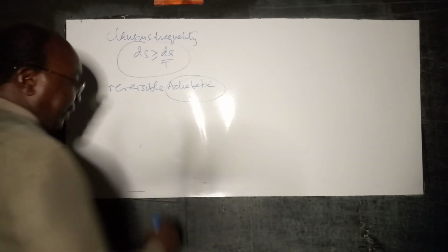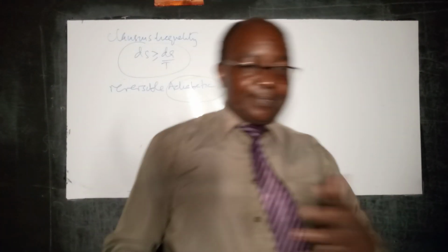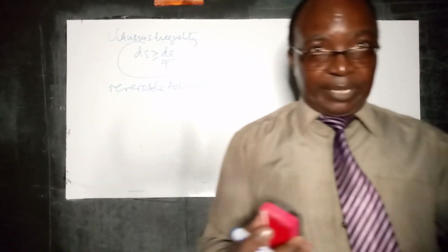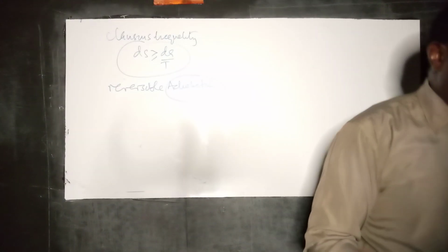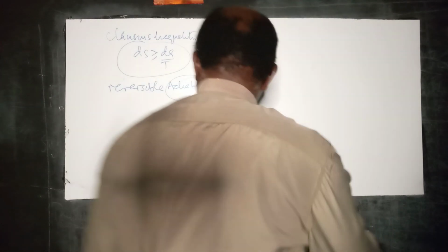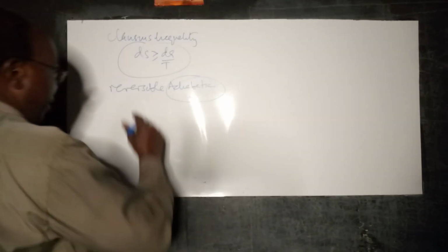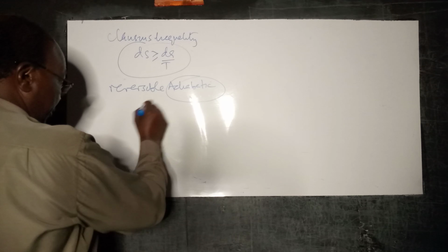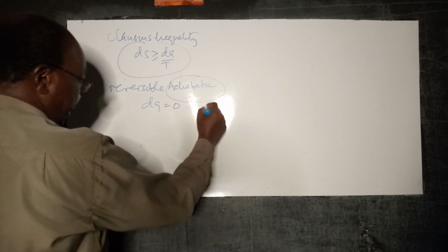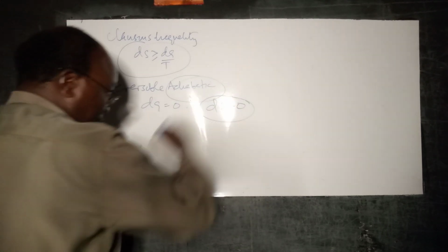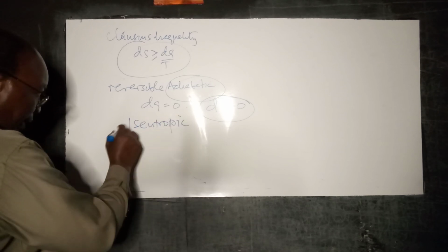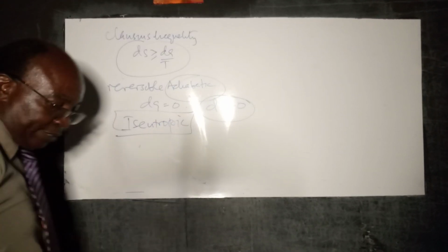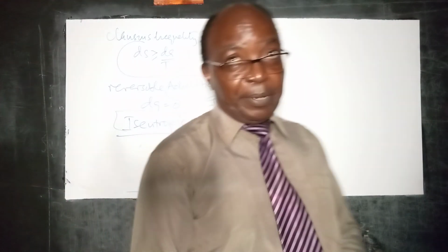And what did we say was adiabatic? It means that heat is not transferred between the system and the surroundings. So if you have steam, for example, then heat is not transferred from the steam to its surroundings. And so dq is 0. Therefore, ds is equal to 0. So that process in the nozzle is isentropic. That's very important for us to know.